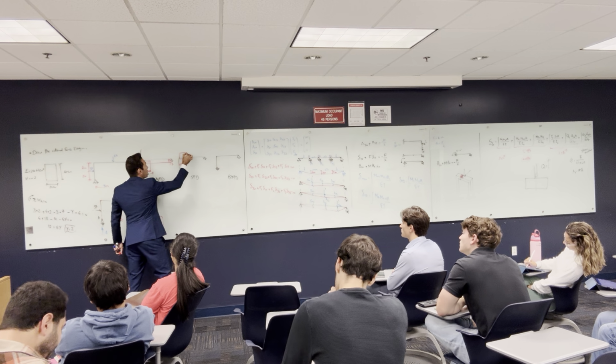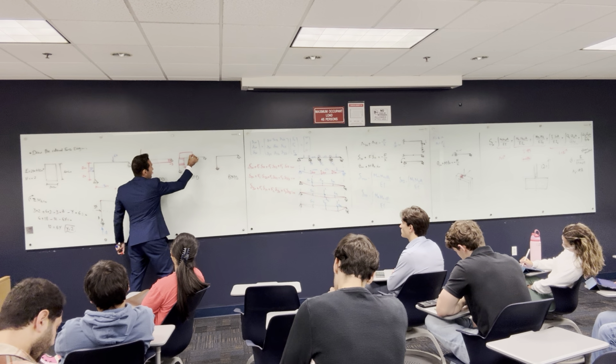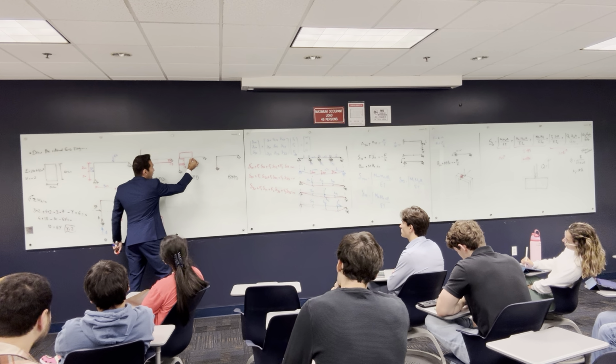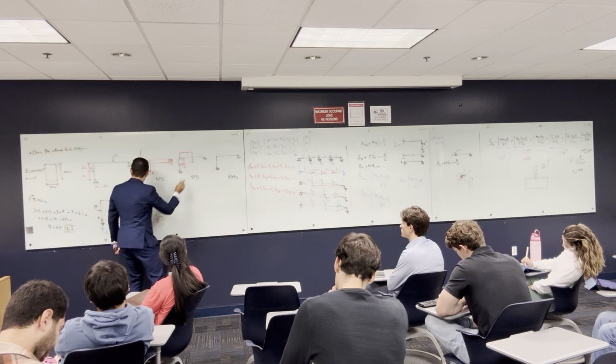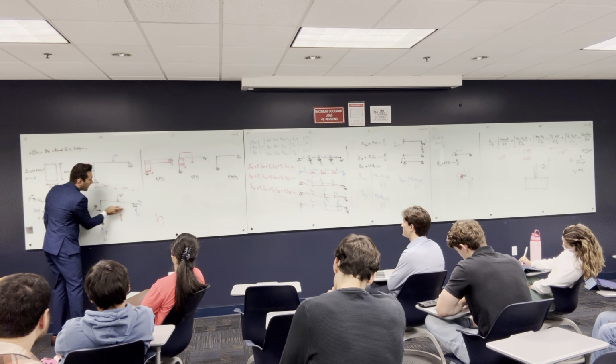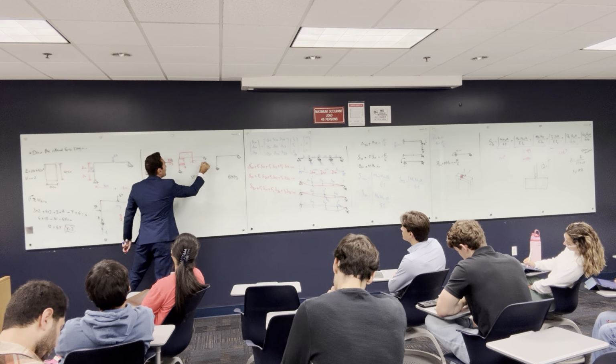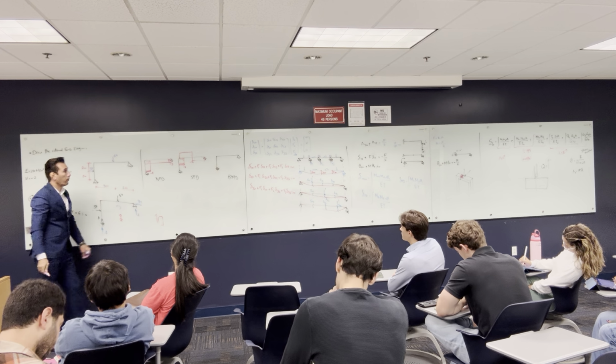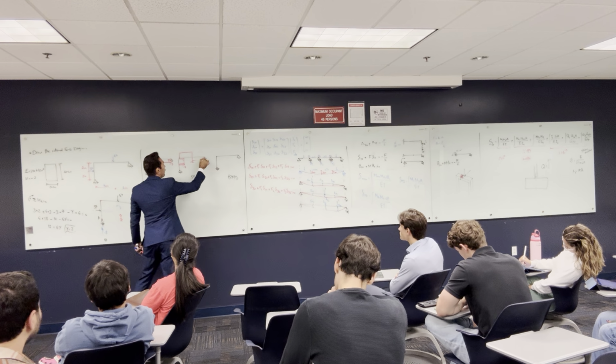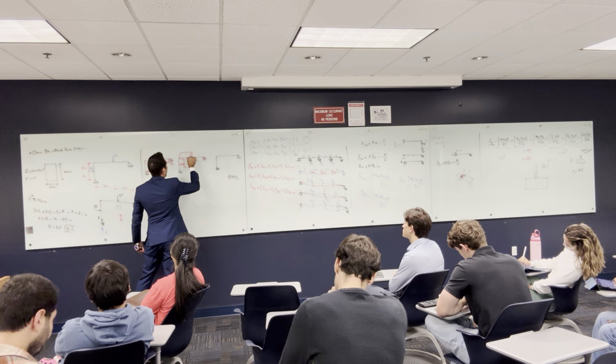I'm going to go all the way until the 6. The 6 is going to take the 4 all the way from +4 to -2, because I'm going down, and then I'm going to go constant until the other 2 bring me up. So that is the shear force diagram.